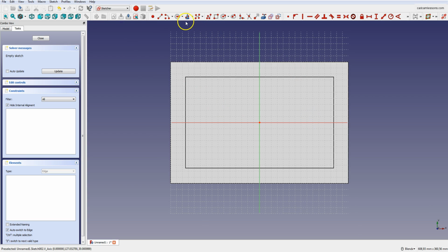and let's draw 4 holes in the corners of the model. To properly orient the holes, we could dimension each hole relative to the origin of the coordinate system, but there is a faster way and an opportunity to get to know new functions. Holes lying along the long edge of this rectangle we can align with each other using the horizontal constraint so that they lie on the same line.